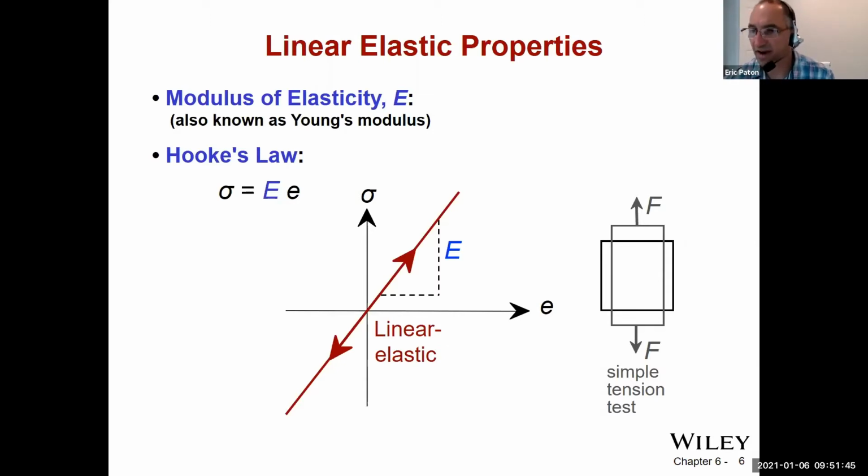Correct, or very close to correct. How strong the bonds are is more of a relationship with the yield point, okay? Because the yield point is when those bonds are actually breaking. But what happens before the bonds are breaking? They're just stretching, right? And they're bouncing back. So that's called stiffness. I guess you wouldn't call it the tensile strength, or the ultimate strength of those bonds. It's more of the strength of those bonds prior to that breaking point, and so we call that stiffness.